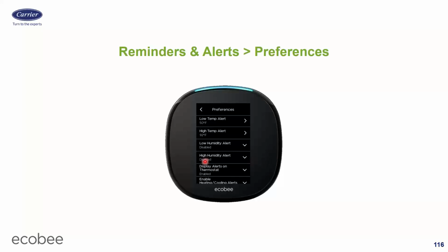High humidity alert. Normally, if I'm the one that sized the system, which usually I'm not because I'm not the contractor, but once in a while I do size someone's system, then I'm going to set this high humidity alert for 65%. If I'm controlling it at 54, which allows it to get up to 59 before it forces my dehumidification mode on, there's no reason it should get up to 65%. Plus 65% is already the threshold I told you from ASHRAE when they start getting concerned about mold growth in cavities and stuff like that. So I'm going to set it for 65%.